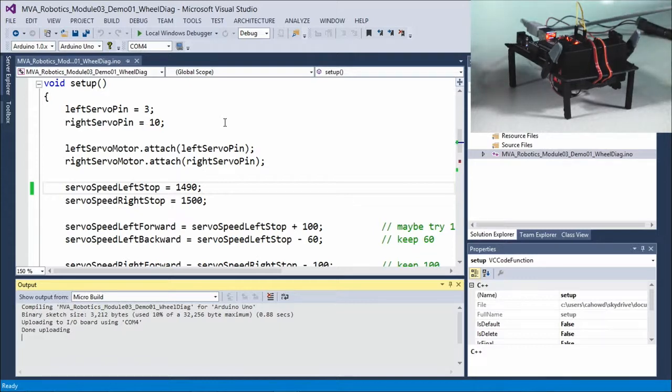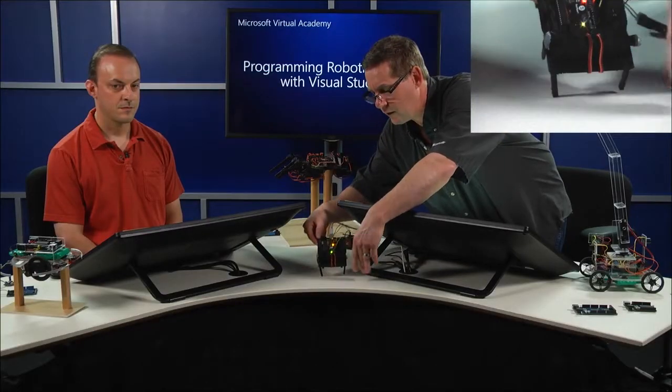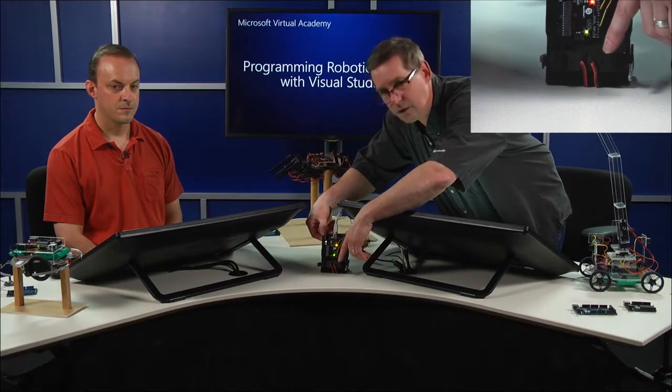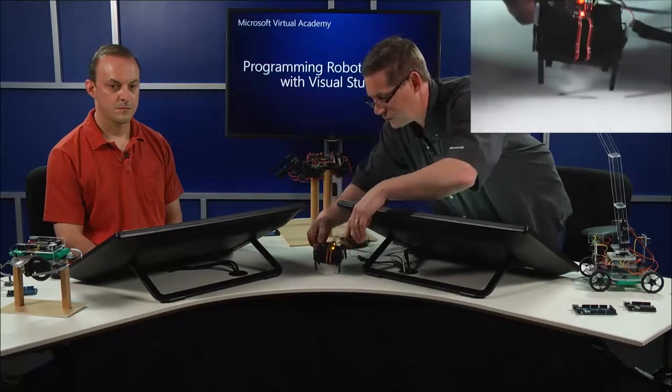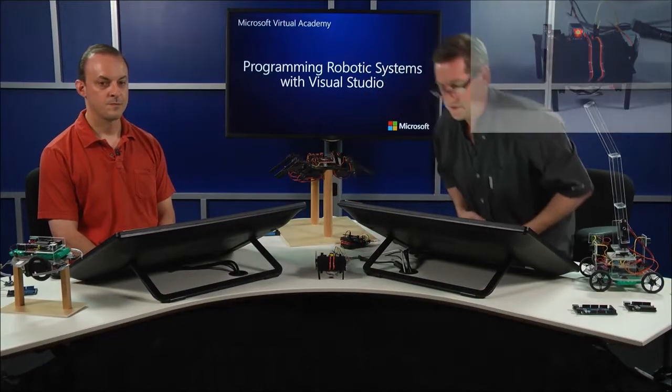You adjust that. We could adjust it in hardware. We talked about this before. These servo motors have a little spot on them. This guy's probably blocked off. I'm gonna tip it up towards the camera, and you'll see the little areas. So do we have a good enough view to see those two little holes? I don't know, maybe not. But there's a little hole right here. There's a screw in there. There's a potentiometer, and you can adjust your zero position. That's good enough. So one of them seems to have stopped. We adjusted that correctly. You use the same technique for the other one.